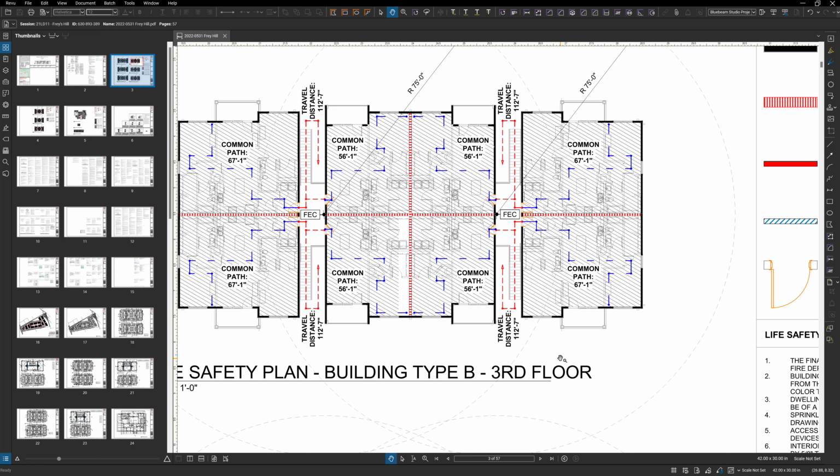So some people believe, based on their interpretation of the code, that these are interior stairways. And when you have an interior stair, you're supposed to build it as basically a fire barrier, versus this particular job where they view it more as an interior corridor that just so happens to have stairs in it, and then they allow us to build it as fire partitions.